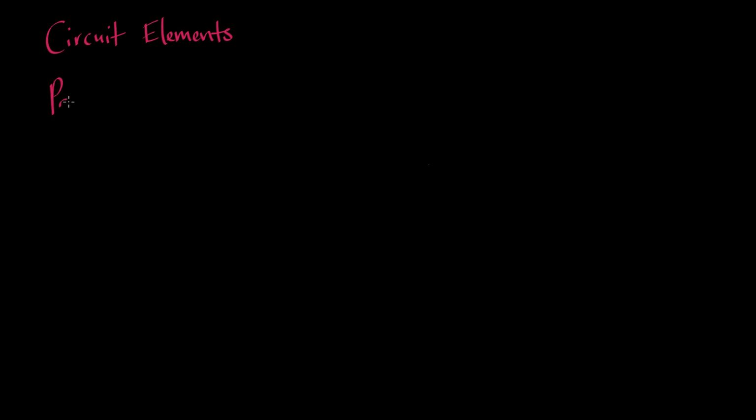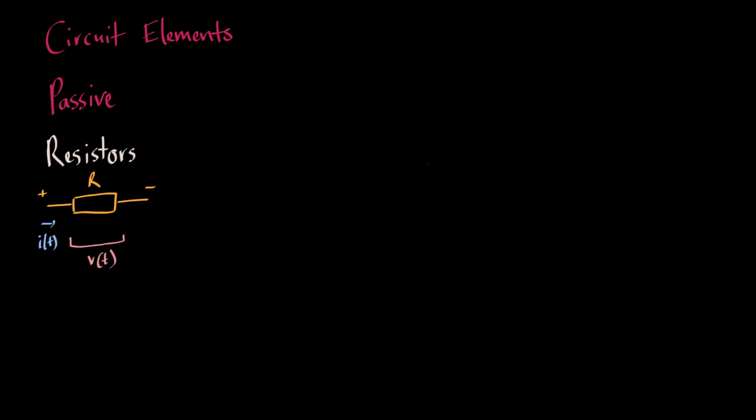Now moving on to passive components, which either dissipate or store energy. Resistors are circuit elements that do the former, opposing current flow and generating some voltage drop in the process. Their representation in circuit diagrams usually looks like this. The time domain equation of the current flowing through a resistor is I of t equals Im cosine omega t plus phi, and its corresponding phasor is I equals Im e to the j phi.